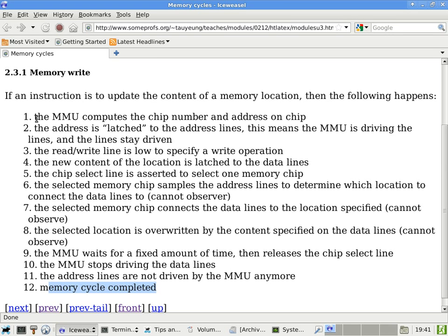Now, if you have to read random locations, if the MMU comes out and you disable the burst mode of read and write operations, DDR2 and DDR3 are no faster than conventional memory, because you still have to go through all these steps. There are no sequential read operations. And as a result, it doesn't help.